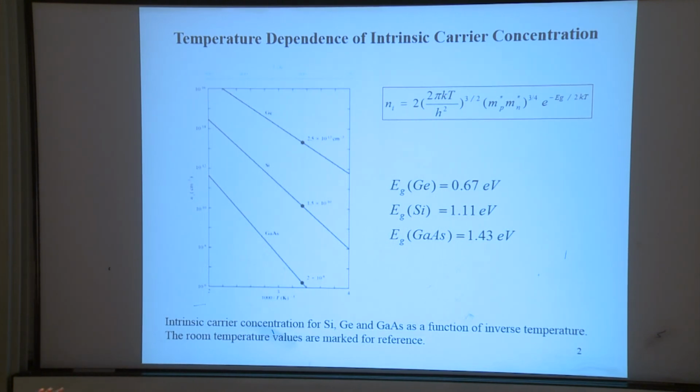So these counteract each other, and the concentration prevails a little bit, not very significantly. It hardly changes the conduction. So semiconductor conduction is not affected by temperature as much as metals. It even increases a little bit when temperature increases, but not significantly.